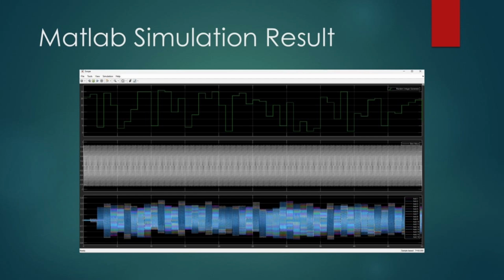And for our modulated output, or the bottom trace, this is the final 32 PSK signal after undergoing pulse shaping and up conversion. Notice that at every 1 second interval, the waveform's phase shifts. These shifts are what actually represent our data.